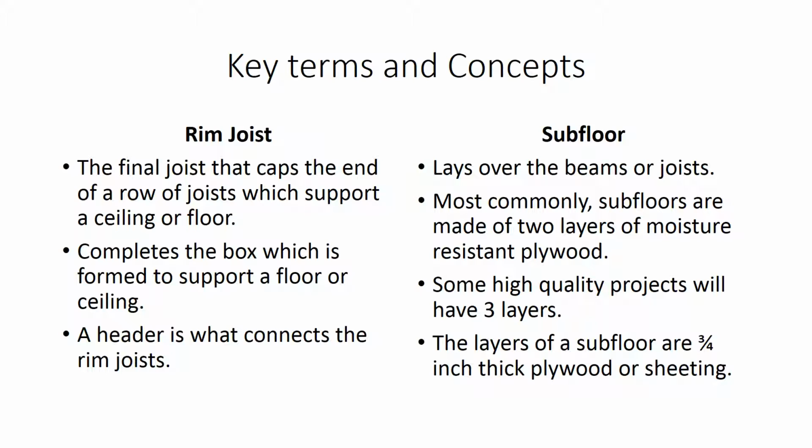Subfloors lay over the beams or joists. They are most commonly made of 2 layers of moisture-resistant plywood. Some high-quality projects will have 3 layers. The layers of a subfloor are 3/4 inch thick plywood or sheeting.